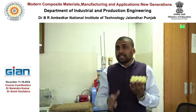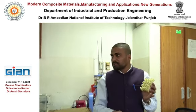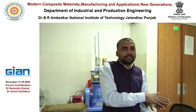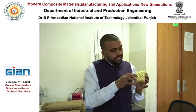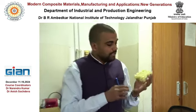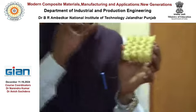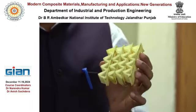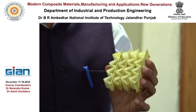In the flooring we use honeycomb type of composite materials, because they are high energy absorbing composite materials. And let's say if there is a void in these structures at any place, what will happen? From there actually your failure starts first. That particular point becomes a stress concentration point.